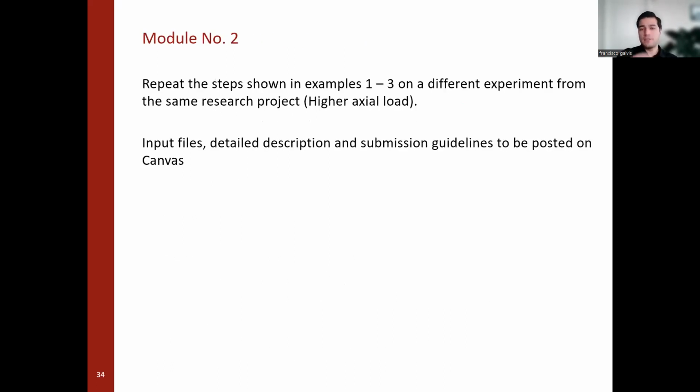So with that, you will have the chance to repeat parts 1 to 3 of this module, but now with a different experiment from the same experimental program that has axial load. That will give you the opportunity to see how the axial load changes the response, how adding P-delta effects also affects the response, and how those values of cracking factor, MP, and MC change when you have axial load. And then you have the opportunity to analyze the nonlinear response of this column that is otherwise identical to the one we did, just having axial load.